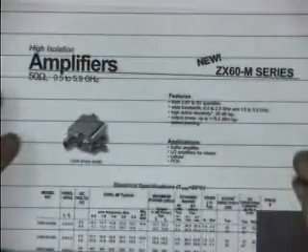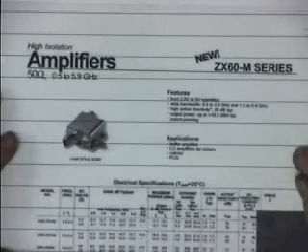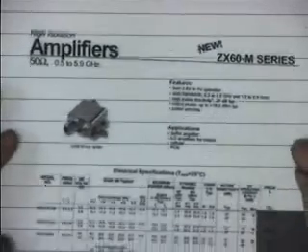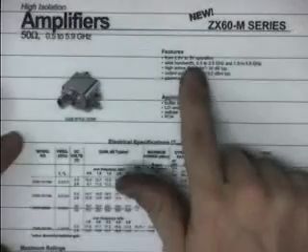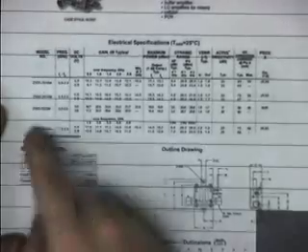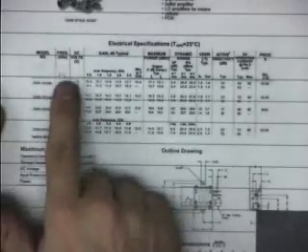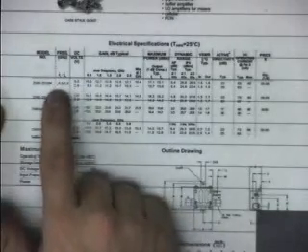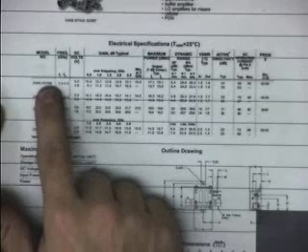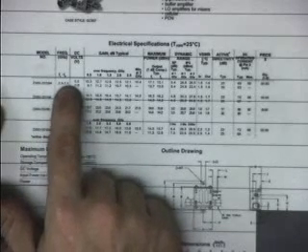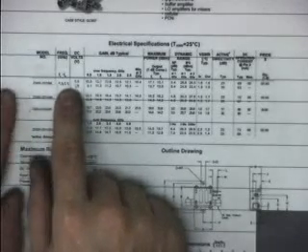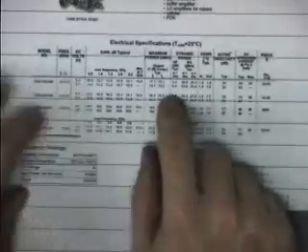Here is this high isolation amplifier. I went and logged on to minicircuits.com and printed out this spec page. You can see that it's got a whole bunch of specs here. There's actually a couple different models, and it kind of teaches you how to read a general spec sheet for hardware in RF. Different model numbers, different frequency bands. Most of these are from 0.5 gigahertz to 2.5 gigahertz, so they're fairly broadband amplifiers. This is the voltage that they take.